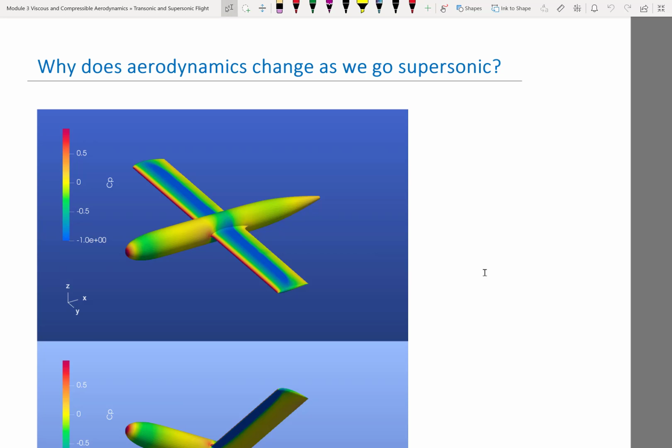Because what is the effect of the suction region moving backward? Okay, what would the pilot feel when the peak suction moves more and more backward? Yeah? It would push the nose down, right? The center of lift shifts towards the tail, right? It would push the nose down.